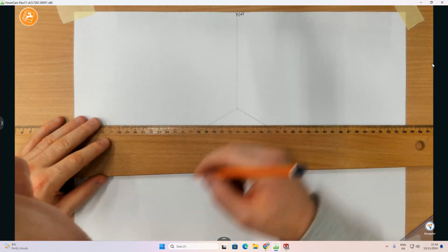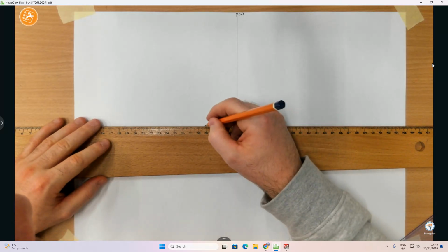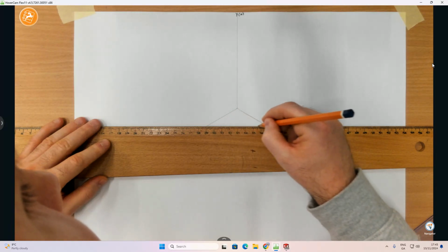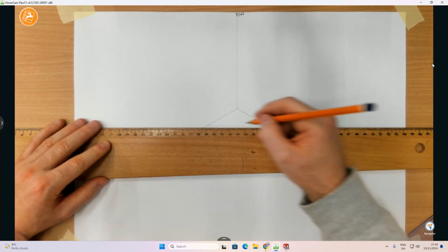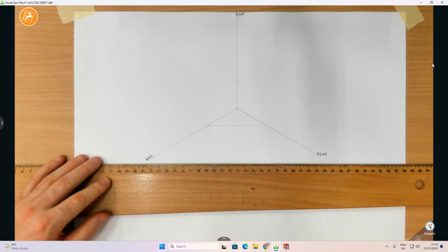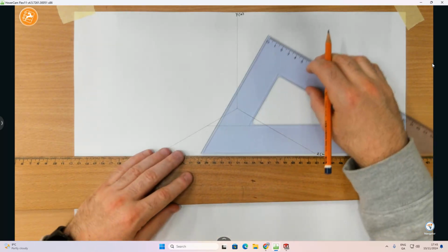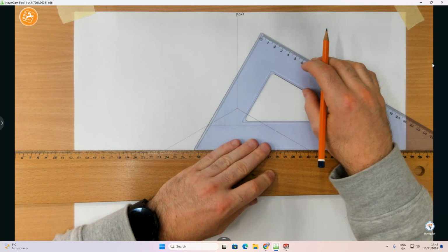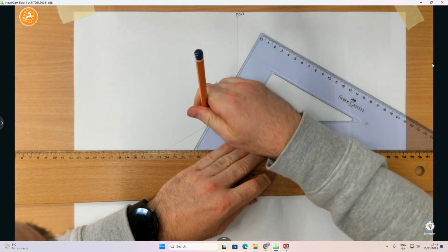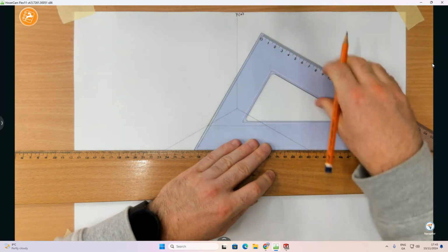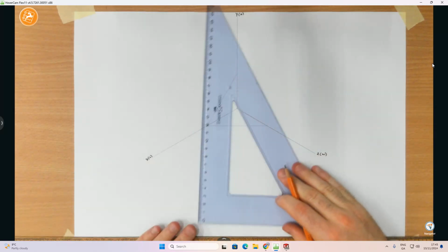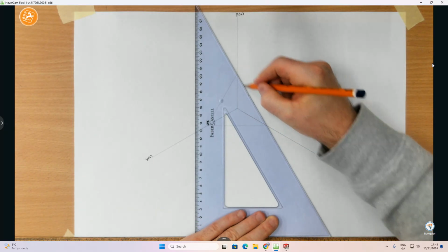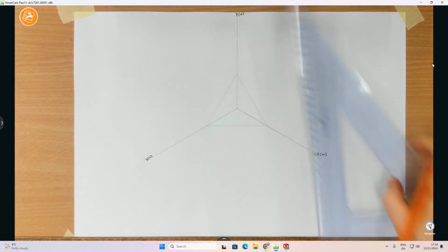In the isometric version, this is always going to be an equilateral triangle. So draw a horizontal line, anywhere at all, it doesn't really matter, you could do it down here. I'm just going to do it here. Don't bring it in too close, because you want a decent sized equilateral triangle. Where it hits the x-axis, I'm going to go up at 60 degrees to hit the y-axis, and then we should be able to draw in our equilateral triangle. And that's after working out perfect.